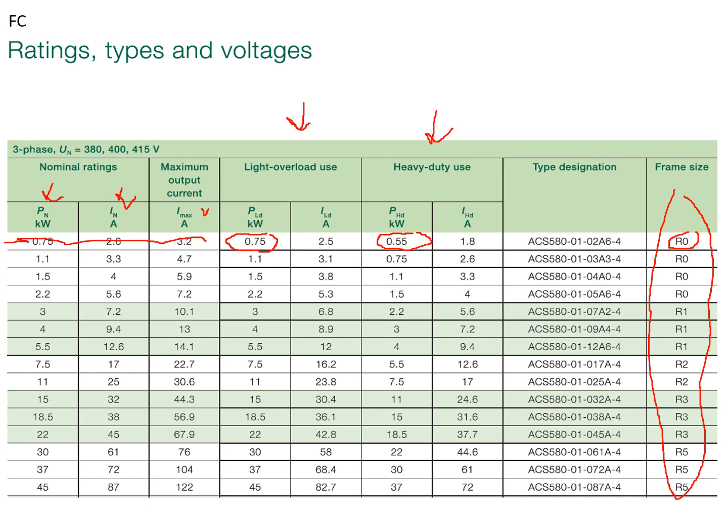So if we have a motor which is rated 1.5 kilowatt, if we are going to run a pump, then this is the kind of frequency converter we need to choose. If we have a conveyor, then we need to take the next one from the next line. Currents of course will be different in both cases, and then the frequency converter will have different rated current.